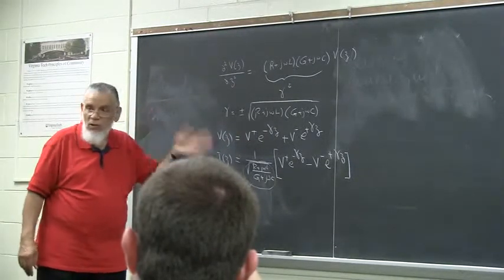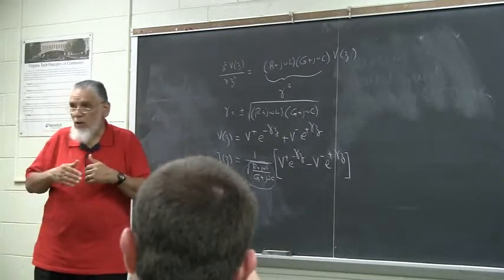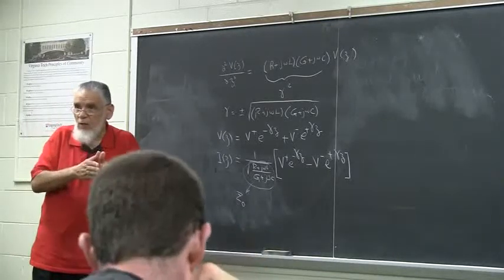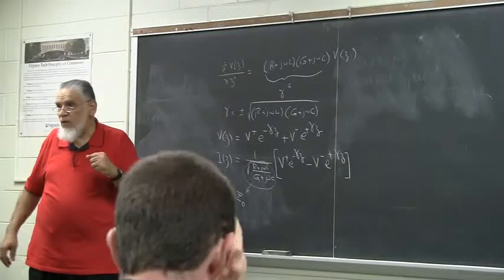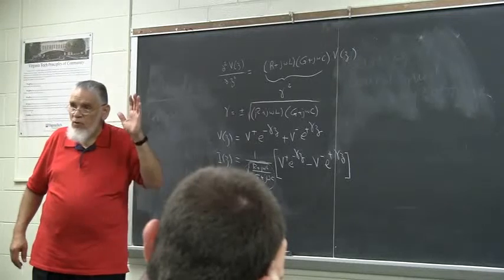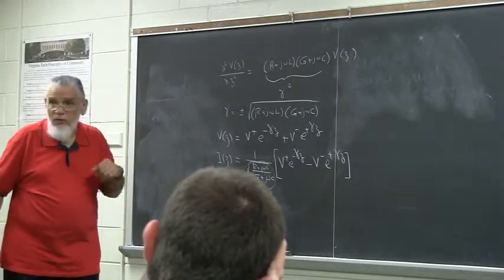So I'm assuming also that we have a homogeneous media. In other words, one location on the line is similar to another location. You are not going to have an R1 here and R2 there, or the dielectric having different behavior from one place to another, or if the amplitude goes up, the parameters change, or if the temperature.